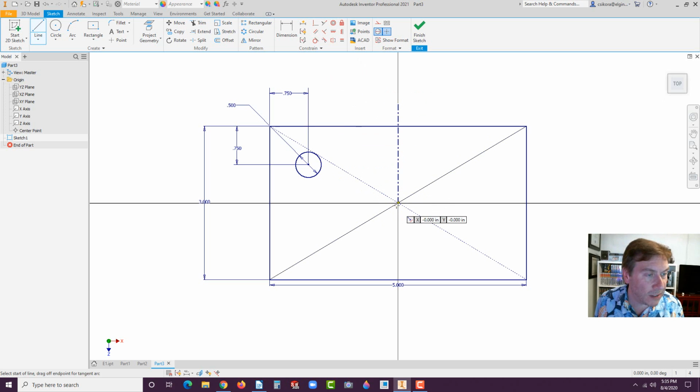All right, now go back to the origin right there. When you get the green dot, click and drag it up horizontally. Click. Now hit escape. Now it's important to turn off the centerline tool, because as you start sketching, if it's stuck on, your lines aren't looked at by Inventor to extrude. It's just construction geometry. It's innocuous. So let's turn that off. Okay. Now, watch this. We're going to look at the mirror tool a whole week early.